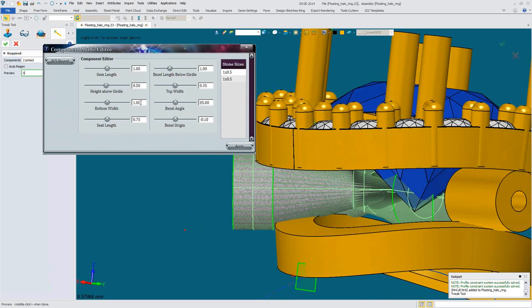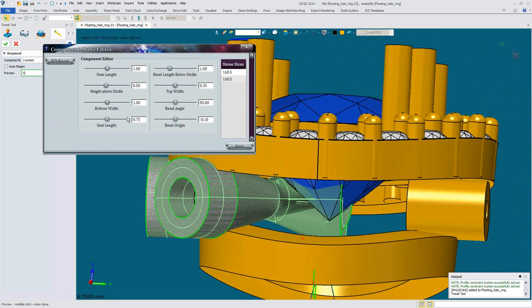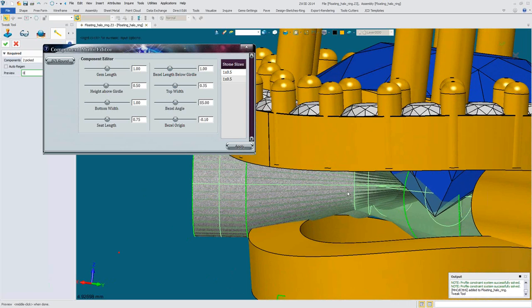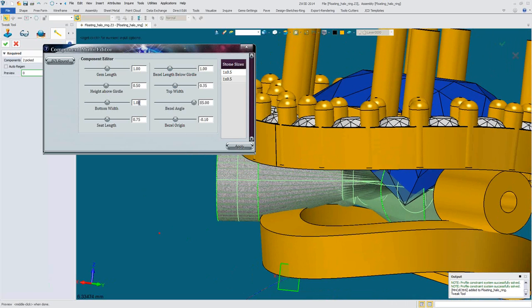You got a slight taper. You got a 1 millimeter stone. If you got a bottom width of 1 millimeter, that means you got one on each side. It's going to be closed. With the angle, it's not only going to be closed, you're going to have it intersecting. So your bottom width, you got to knock it down to, let's say, about 0.45. We'll see how it goes.